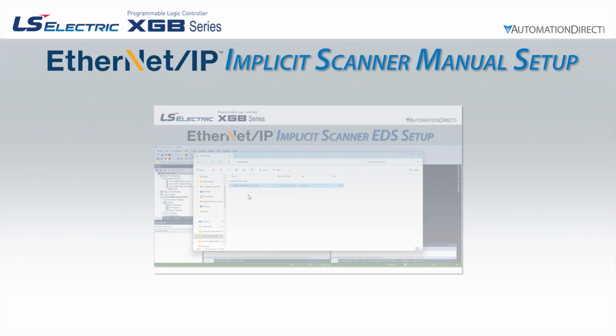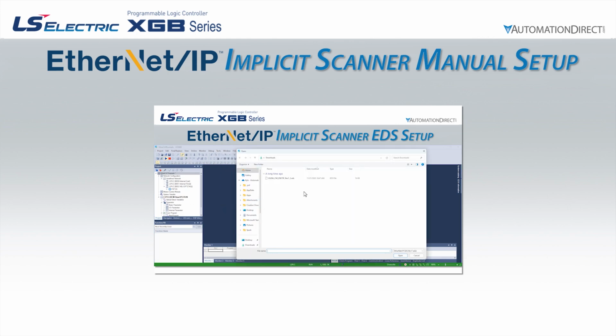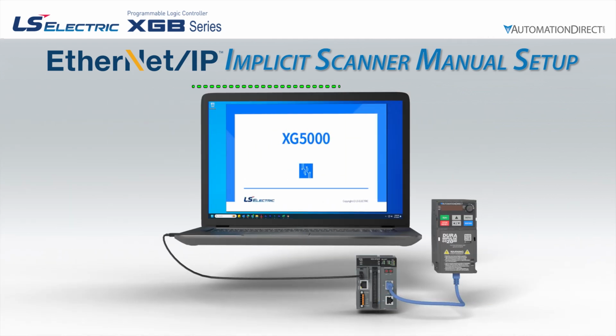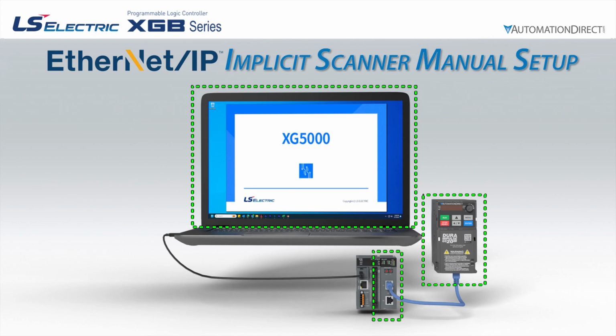In our previous video, we set up the XGB PLC as an implicit scanner using the EDS file for the GS20 variable frequency drive. In this video, we will be using the XG5000 generic EDS file to manually configure an implicit scanner connection and message in the XG5000 software. This will also allow the EIPT module to communicate with and control our GS20 variable frequency drive.